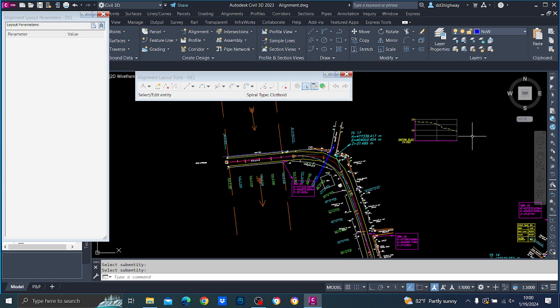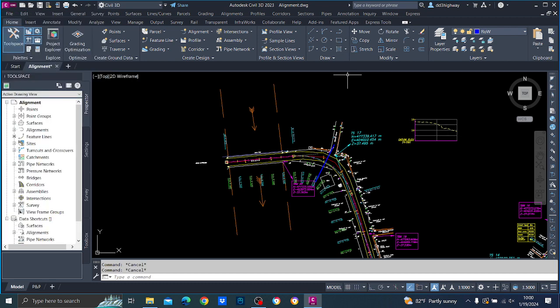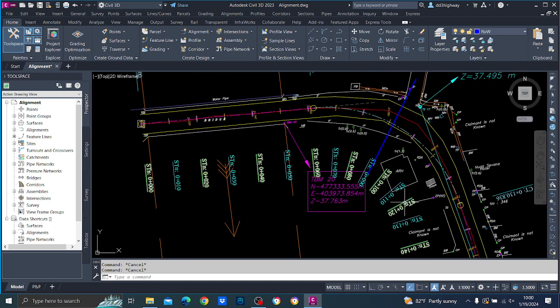So you want some practice. With the practice you can decide whether it is okay to improve this or not. Okay, right. Then the other thing is usually we don't give chainage labels at each 10 meter intervals. Sorry, 20 meter. Yeah, at each 10 meter intervals we don't give this detail. So what you can do is, we want to switch off, not delete, these things.